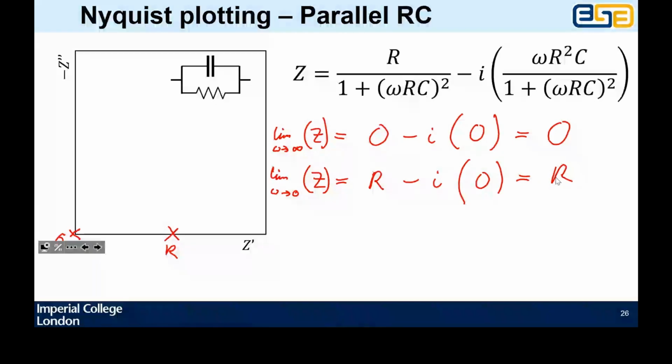There is a nice value of omega that we can pick that simplifies the equations. Look at those equations, and think about a value of omega, frame it any way you want, that would make lots of bits of the equations evaporate into dust. Can anyone think about it? What value could omega have that would cause bits of the equation to disappear? Well, look, what is omega multiplied by often? It's multiplied by RC. So if omega was 1 over RC, then 1 over RC times RC is 1.